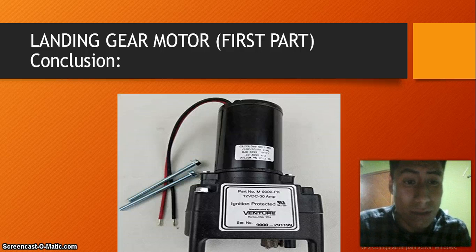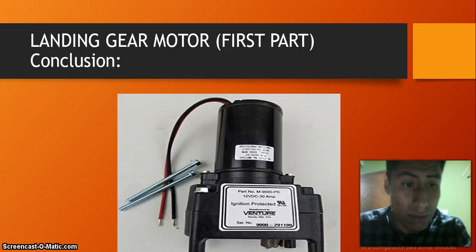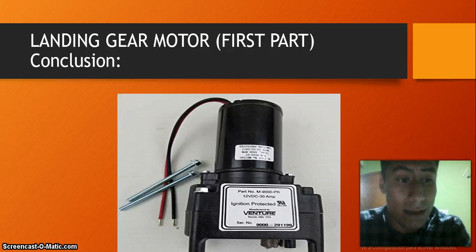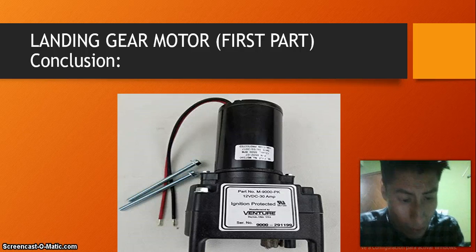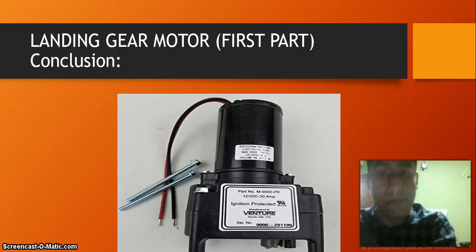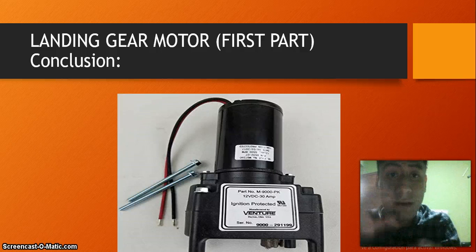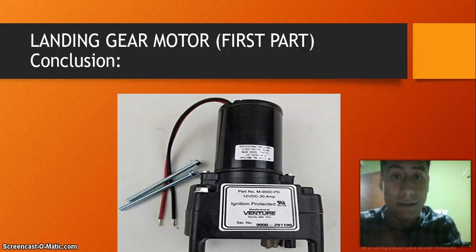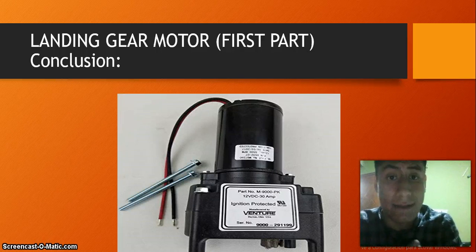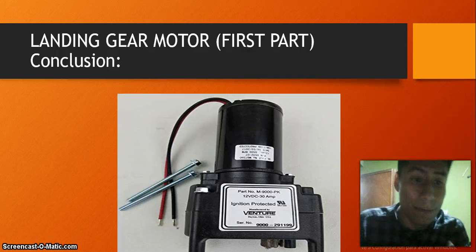The connection points of the brake cables were identified in the coil. To verify the status of the connections, a resistance measurement test was made, for which this diagram was taken into account. Part of this diagram I mentioned in my report: the specific components analyzed in this first part. We first analyzed only the motor and the brake coil.